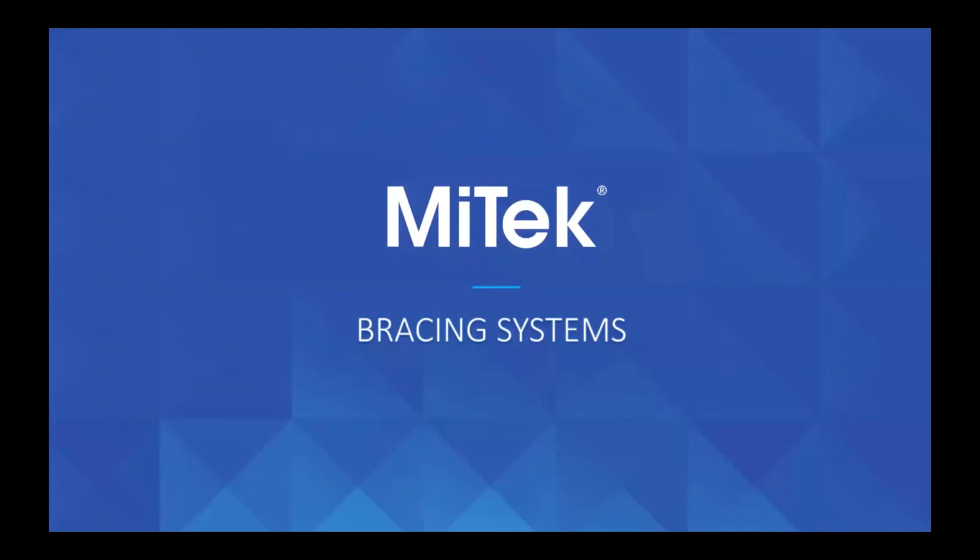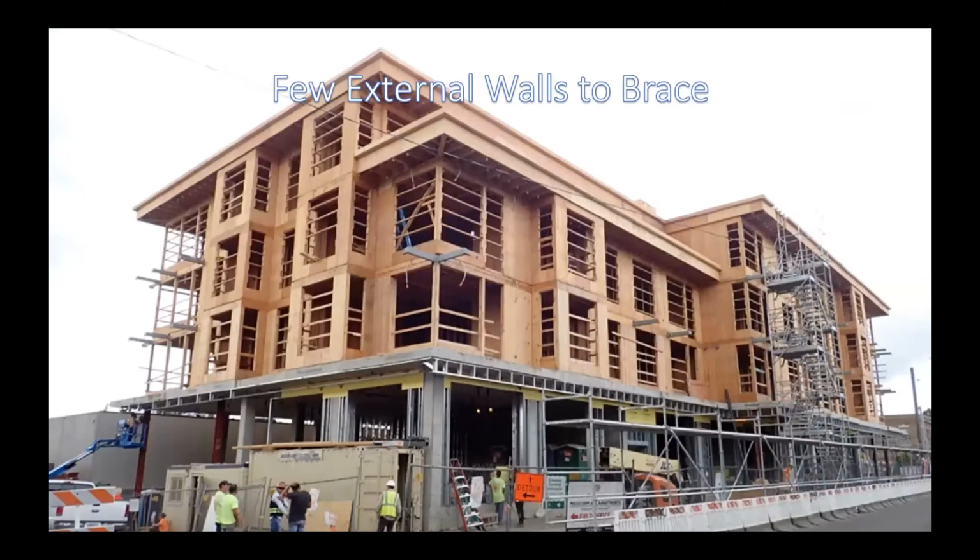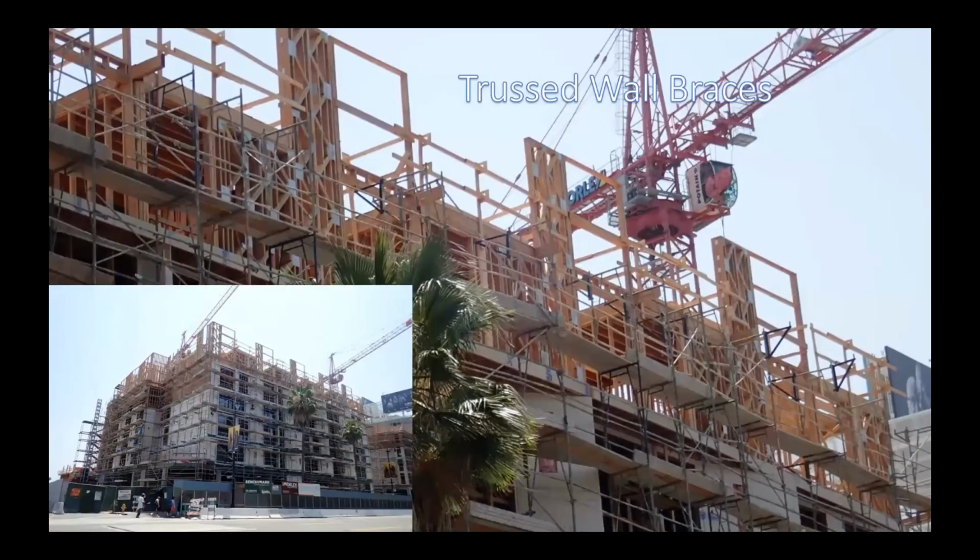So, how do they brace these buildings? The first thing you'll note when you look at all their buildings is that they've got very few walls. Most of it's all openings, as you can imagine. And that's the sort of thing we do encounter. So we have to deal with the fact that there's not necessarily a lot of walls to brace with, and having to be able to accomplish that is a challenge. In the first building I showed you earlier, we saw the use of trusses as bracing panels in walls, and that's one way of accomplishing it.